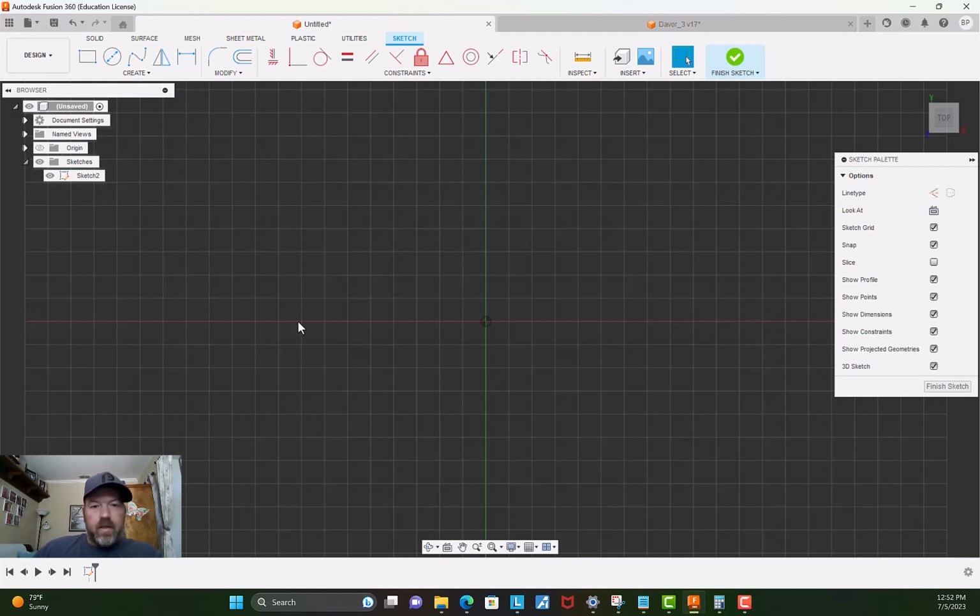But sometimes that's a little cumbersome, especially if you have ring widths that change on different builds. So I think the best way is to calculate the tapers per inch and then the taper angle for your cue. And then you can just draw directly on here with that taper angle already included.